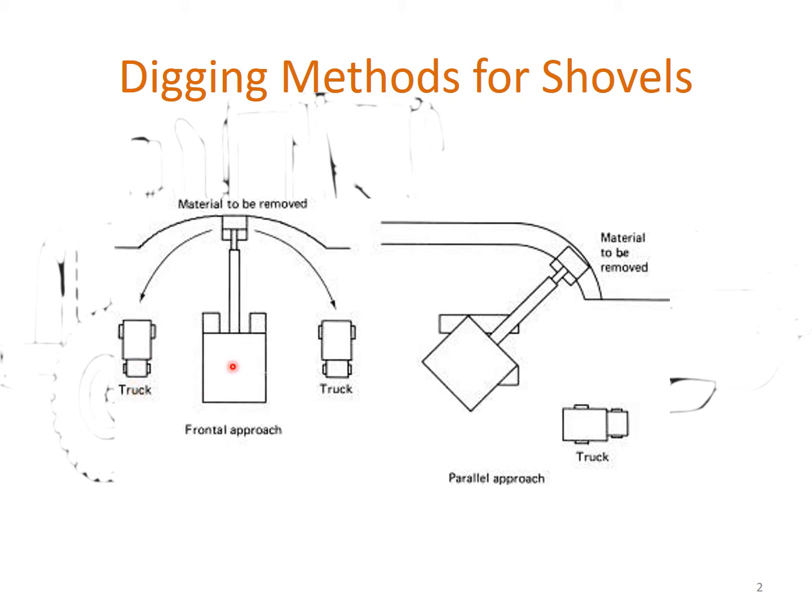of the site, and the shovel keeps moving forward to get the material. The second method we call parallel approach, when the direction of the shovel, as you can see here, goes to the right, and the direction of the material to be excavated also moves to the right, in parallel. That's why we call it parallel approach.